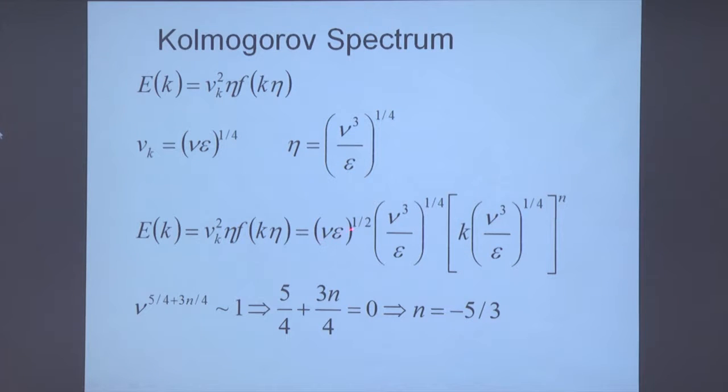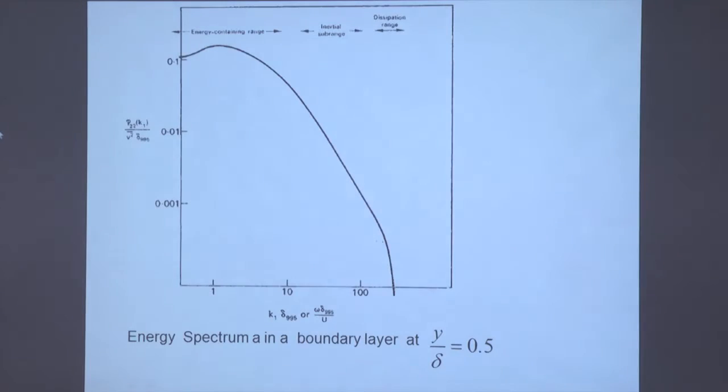And he rewrote that now. He combined all those viscous terms there. If you combine all the viscous terms, it takes this form. He found that when those viscous terms vanish, the power, the index, goes to 0. That corresponds to minus 5/3. Okay, so the region where we saw in the last slide, the power law intermediate region, is independent of viscosity and is also isotropic.